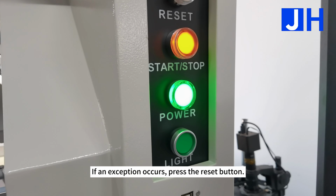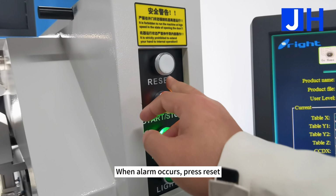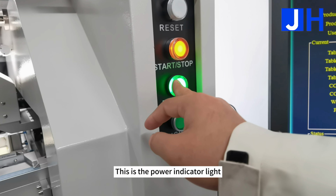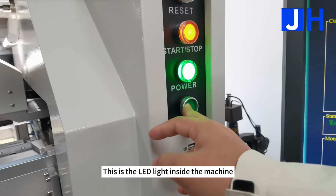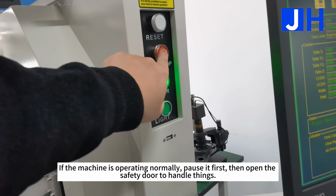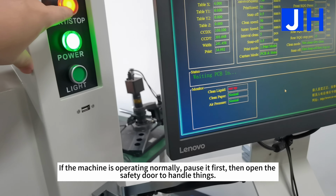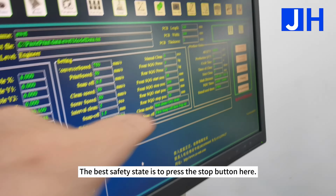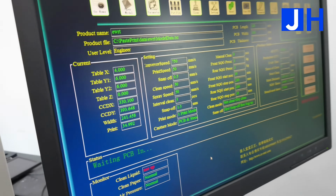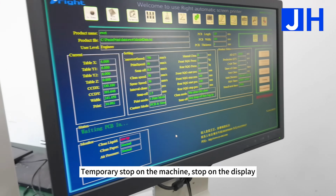If an exception occurs, press the Reset button. When an alarm occurs, press Reset. Pause and start. This is the power indicator light. This is the LED light inside the machine. If the machine is operating normally, pause it first, then open the safety door to handle things. The best safety state is to press the Stop button here. Temporary stop on the machine, stop on the display.